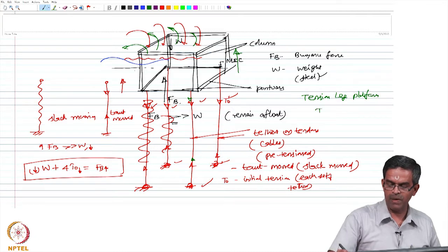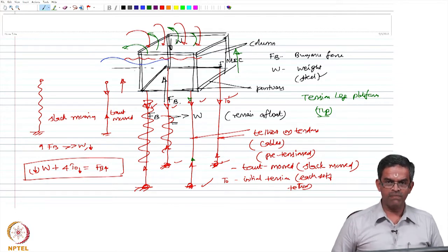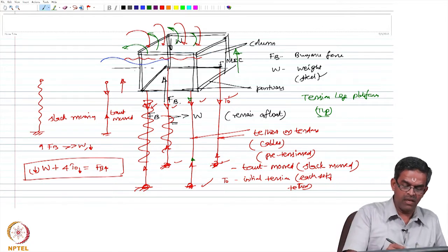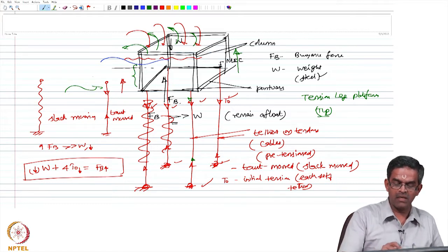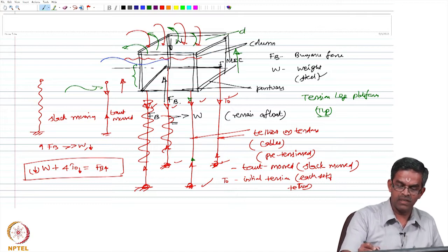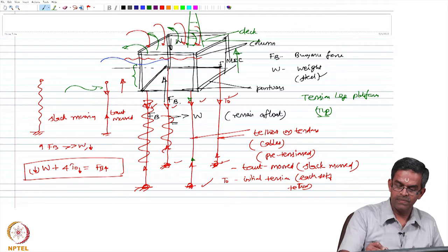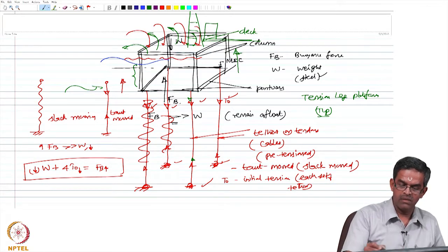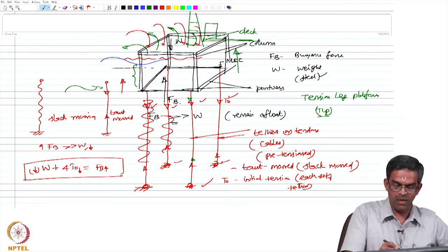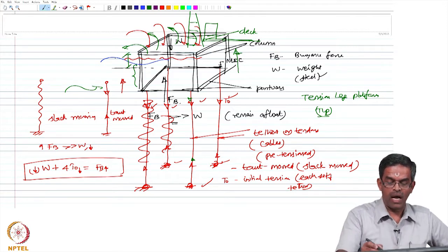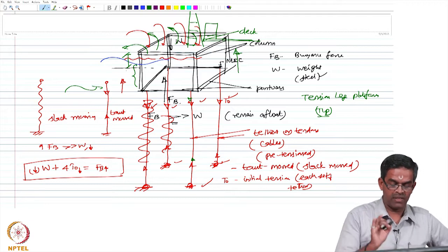Okay. So, this is a typical offshore compliance structure which is useful for deep water oil exploration. There are many advantages of the system. In case of any lateral load hitting the body, only this part of the body is submerged. So, the wave action on the body is minimum, because the deck, where all operational features happen, the derrick, the living quarters, etc., is above water, and there is enough freeboard available for this body. So, the action of production and drilling is not affected by the splash or by the wave effects on the body, number 1.